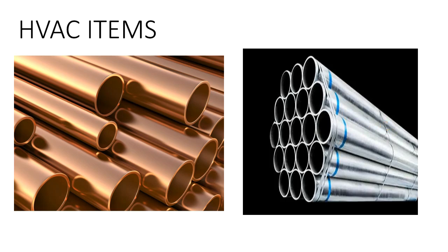For chillers, in most cases you'll be using black steel pipe or carbon steel pipe. In some cases, for example a water cooled chiller or a district cooling plant, you will be using the GI pipe. This GI pipe will be useful mostly for outdoor application, as in if you are transferring water from the condenser to the cooling tower, you will be installing these pipes.